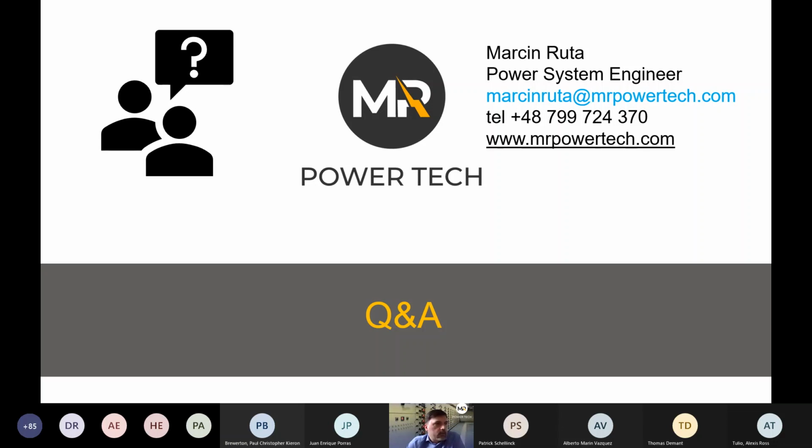How much do we need to carry out arc flash studies on temporary equipment, for example low voltage rental generators and distribution? If you will be working live on this equipment, it would be nice to have. And you can do it on the generator itself, because the generator will be the supply. So if you calculate it for your generator, on the generator outgoing, probably this will be enough. Otherwise, you have to recalculate the whole site assuming a generator is connected, which is sometimes done when we already have information about what kind of generator might be connected. But I would say this is much easier if you calculate it for your generator itself.